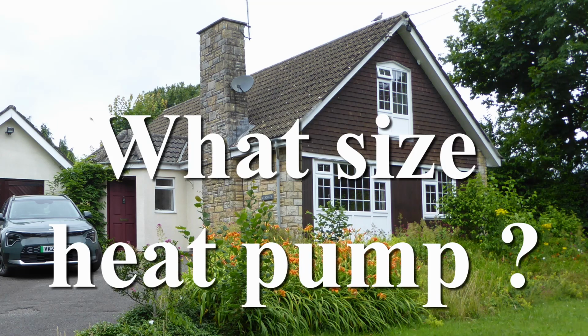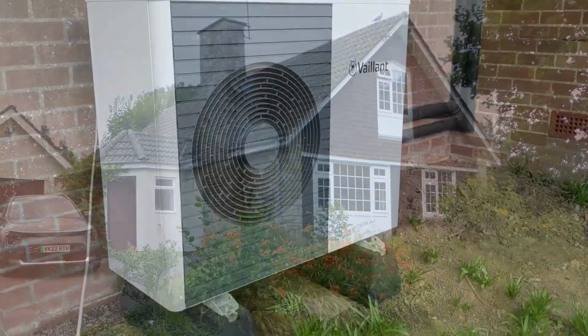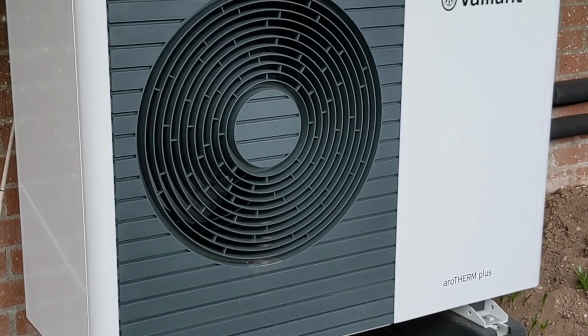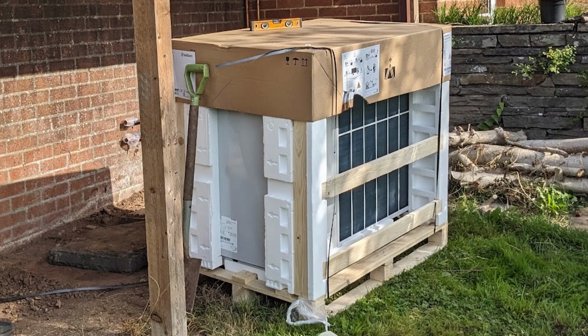If you want a good installation, you really need to understand the heat loss from your property. Most installers err on the side of putting one in that's too big. If you come from a tradition of gas boilers where you have enormous ones, we had a 36 kilowatt gas boiler and replaced it with a 7 kilowatt heat pump, and I think they're just uncomfortable making that switch to a different form of heating, so they'll say, well, we'll give you a 10 or a 15, which, for this property, would have been far too big.